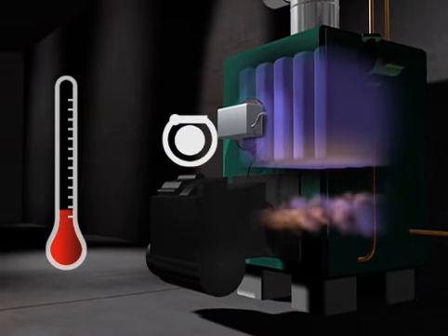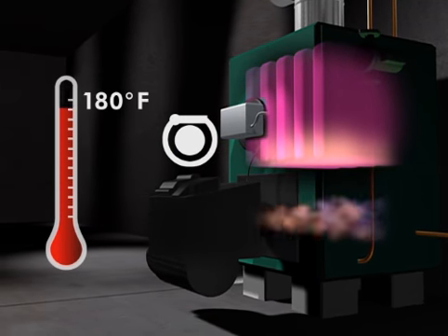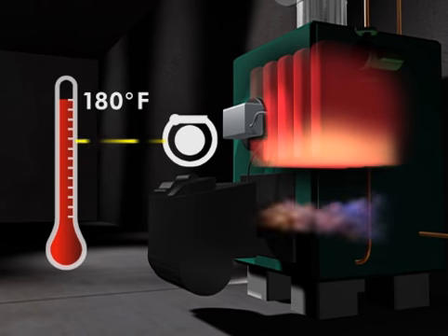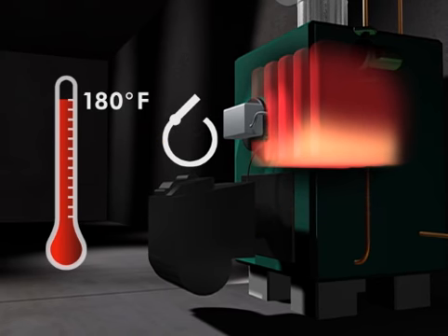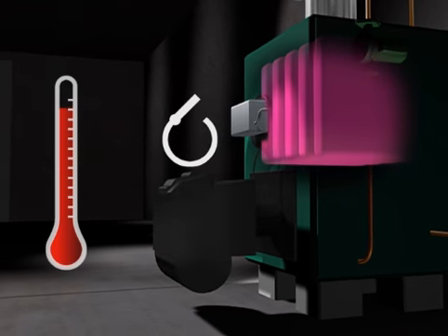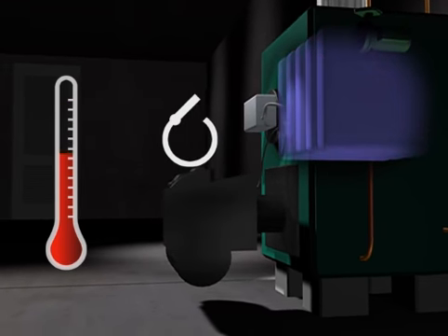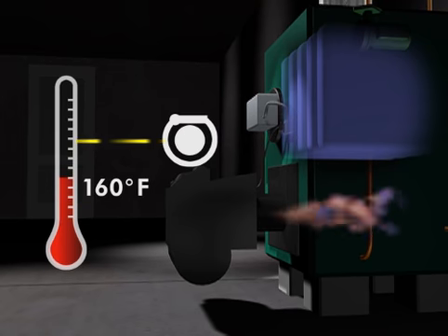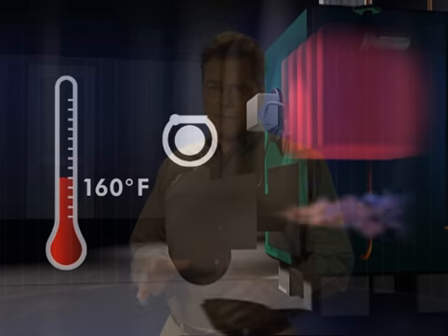When the boiler water temperature rises to the set point that has been selected, typically around 180 degrees Fahrenheit, the electrical contacts of the aquastat open, opening the circuit and turning off the burner. When the boiler water temperature drops approximately 20 degrees below the set point, the contacts close again, turning the burner back on. Typically, when there is no call for heat, the aquastat maintains a boiler temperature of approximately 130 to 160 degrees. For systems that incorporate tankless coils, it's necessary to maintain a boiler temperature sufficient to ensure that the system can provide adequate domestic hot water.